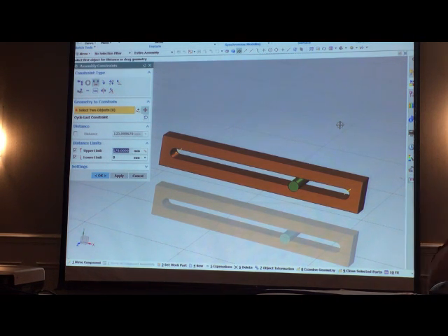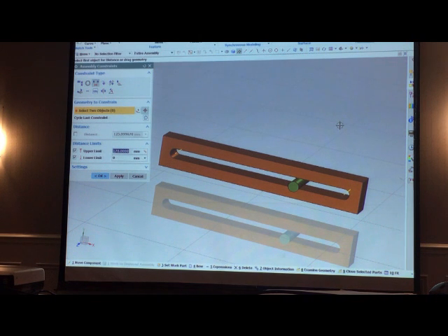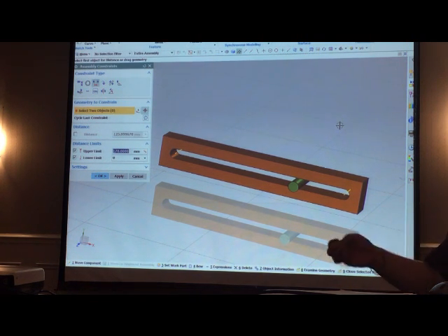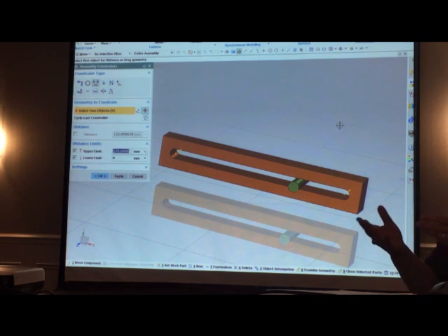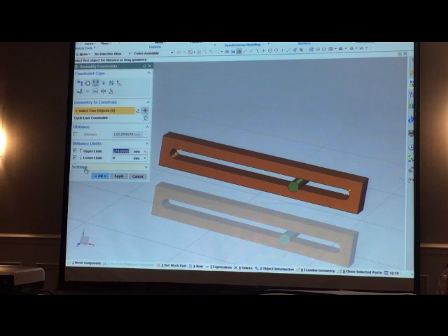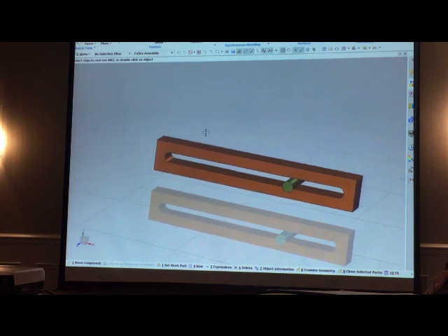you can now control these limits, where in this case I'm simulating a physical limitation, whereas in the first model it was strictly a logical limitation. Nothing was preventing that valve from going all the way around. I just only wanted to stop it at fully open or stop it at fully closed. Here I'm mimicking a physical limitation. And I use a measurement so that as the part changed in size, that physical limitation changes, and therefore the constraint changes. So think of what you could do now with assemblies. That would be interesting.